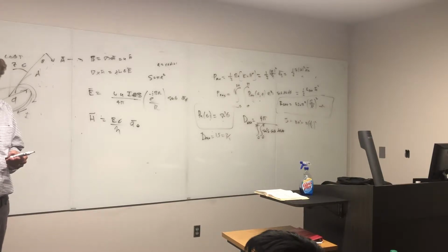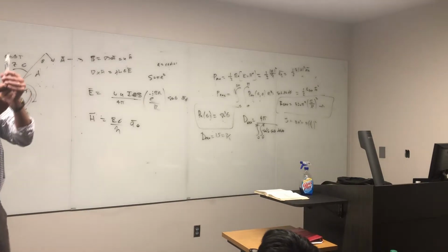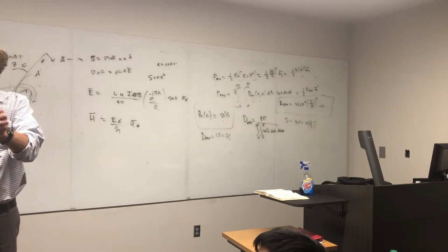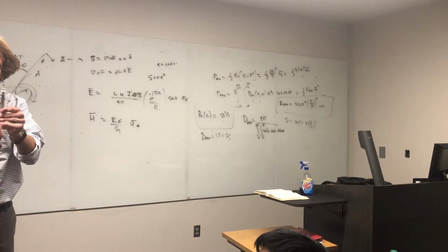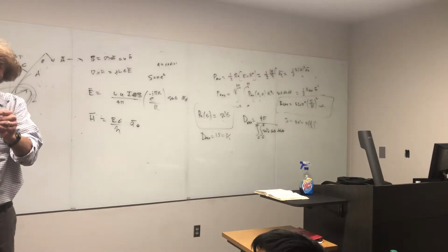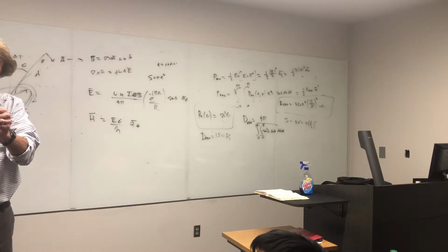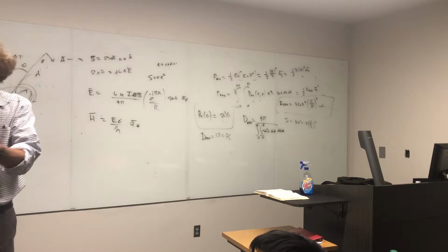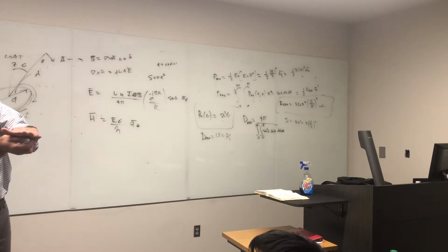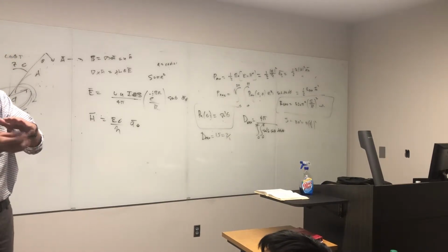The problem with dipole antennas, a lot of times, is a dipole antenna needs to kind of be sticking out. Usually they'll put a dipole and it'll be a metal plate back here and you get what's called a current image below it that will make it look like a dipole. But the thing is that they stick out, and when you embed them, like in phones and stuff like this, so they're buried, any metal next to them will interact and cause an impedance change and cause problems.